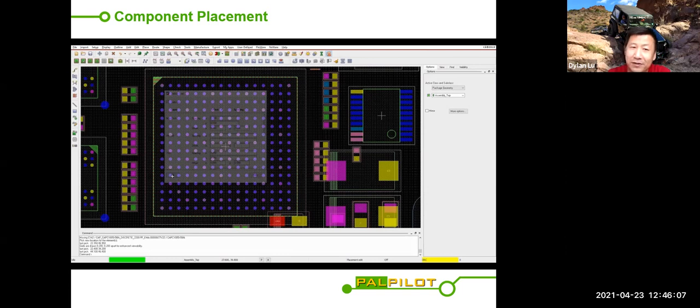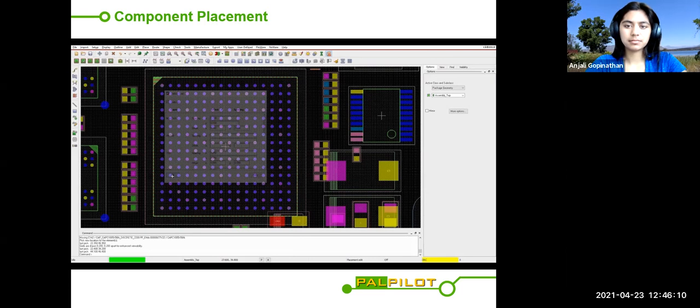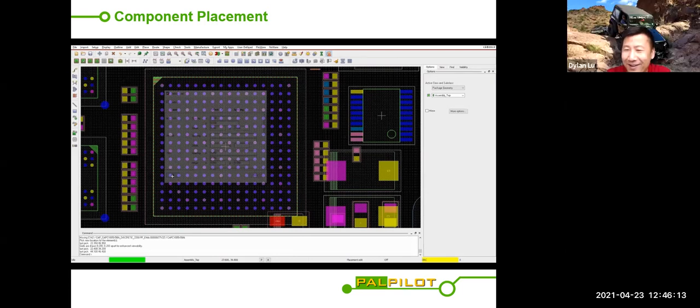And if it already adds layers, it's gonna utilize that layer. So it will redirect other traces to use that layer. And if you want to redo it, it will take you more time. So a lot of time with a complex board, once you click that button, you probably need to sit there doing something else, or pick your teeth, or watch another YouTube video for it to finish its work. Sometimes it's hours. And then when you come back, you think, whoa, it didn't do the way that I wanted. And you reset up the constraints and click that button again, wait for several more hours and come back, hopefully just right this time. So for us, we just use manual routing.